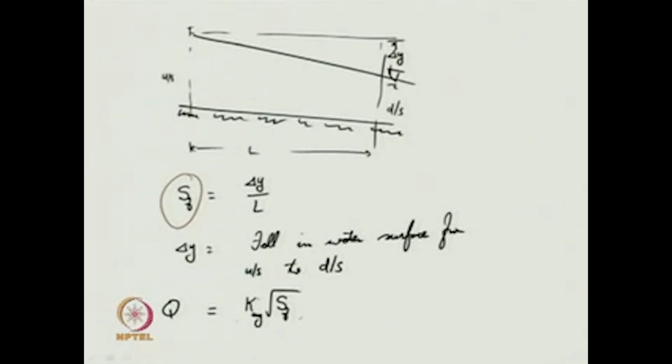Please note that we had given an approximation for the energy slope and we are substituting it. So, let me give this as a first approximation. This is not the actual correct flood discharge from the channel. It is just a first approximation. Now, using this value of Q, you can easily evaluate the velocities at the upstream and downstream, right? Uniform flow means generally the discharge is the same at upstream and downstream.